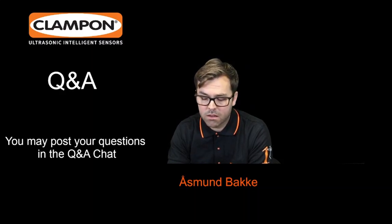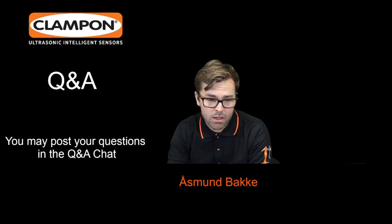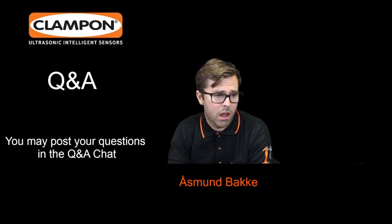Yeah, that's a very good question, because if we go 20 years back in time, then we didn't have flow meters which could give us good flow data, and still there are many wells out there which don't have a flow meter, and we are used to using allocated well test data. We have different solutions there, from a fixed lookup table in our software where we can define it, to an SQL link where we are picking up these allocation curves directly from the operator's database, etc.